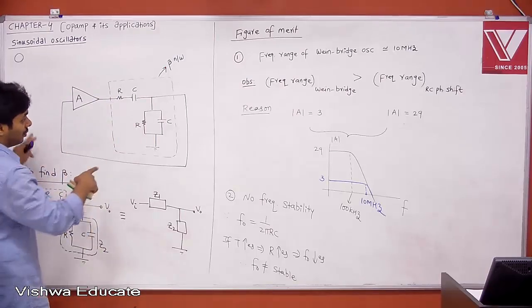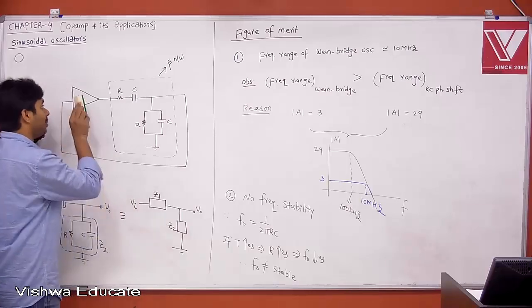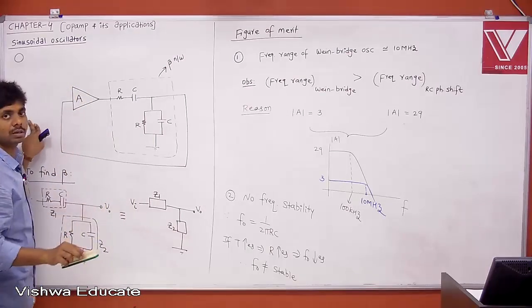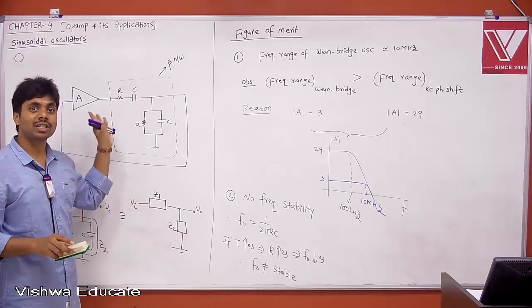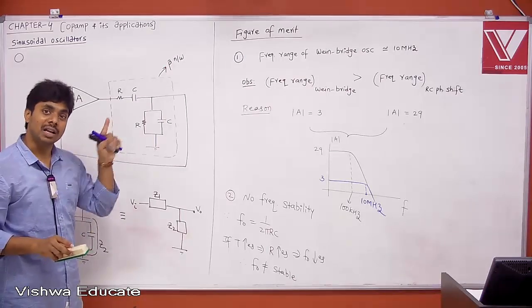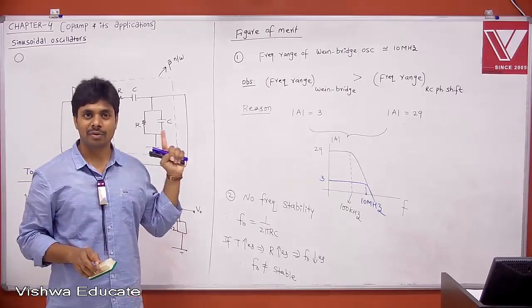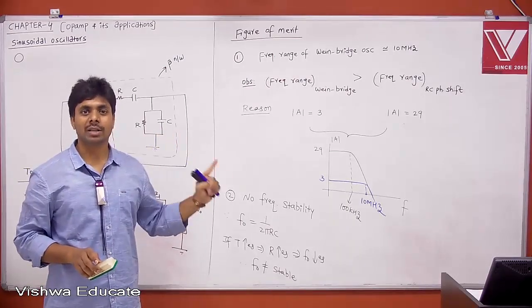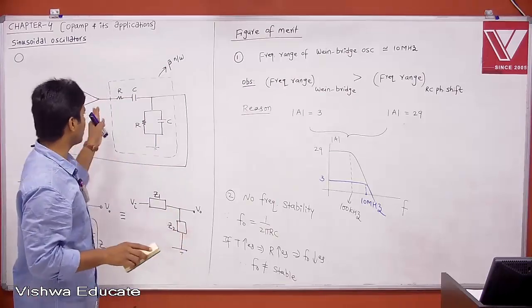But now, if you consider a beta network where there is no resistor, then the output impedance of your op-amp will come into the picture, because now the beta network doesn't have any resistance. Then whatever resistance you have from your open loop amplifier, we need to consider. Therefore, for the third circuit, assuming that the beta network does not have any resistor, your op-amp has some output impedance.